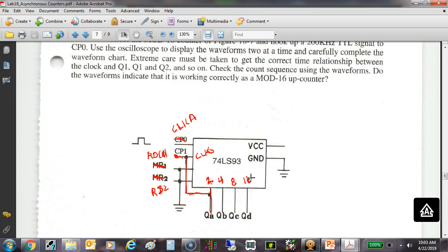I have these hooked up to switches. I'm sorry, I didn't change those. So we can see these happen. They've got them both connected to ground. I have both of my switches down to low. It doesn't make any difference. One could be high, one could be low, because it's a NAND circuit, right? So to reset it, I have to bring both of them high. I have this one hooked to switch 0 output on the trainer, and I have this hooked to switch 1 out.